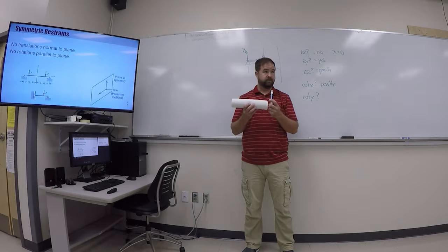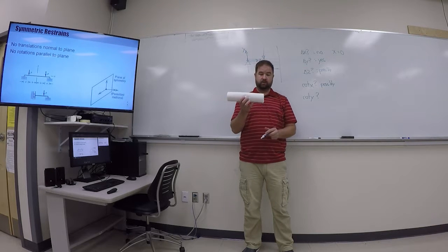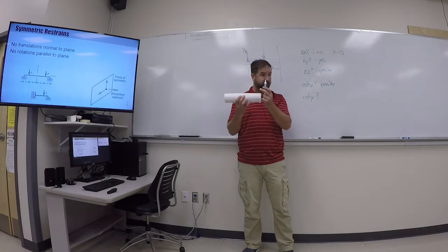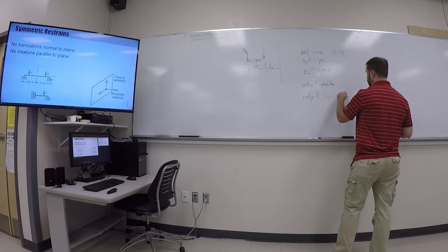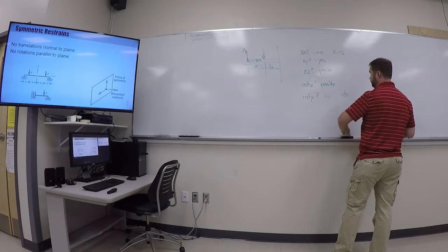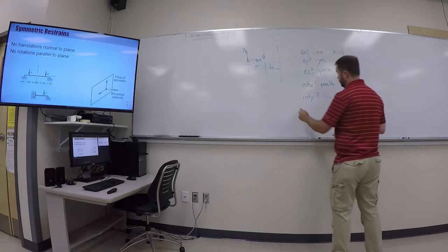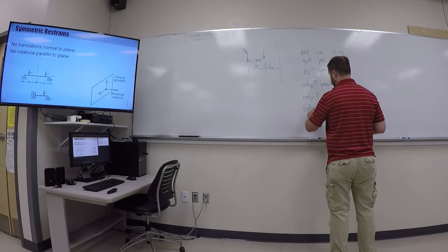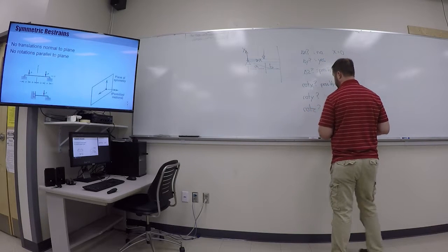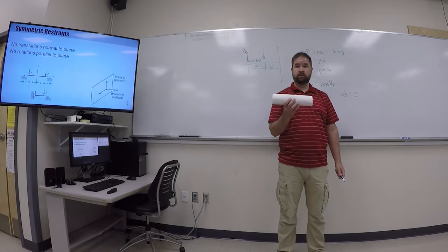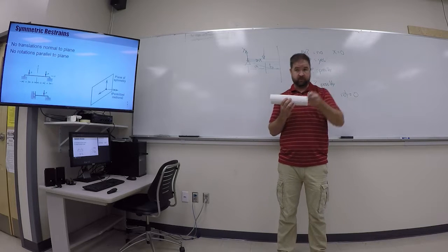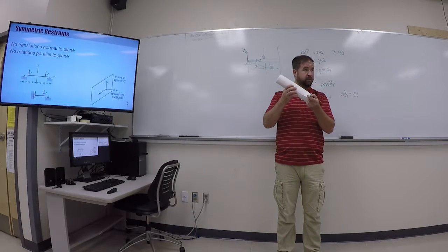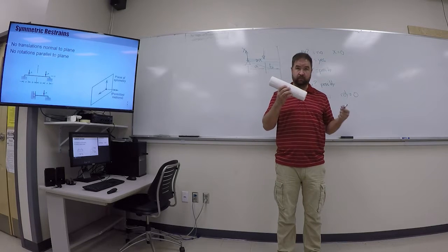Okay? Now, can I have rotations about x? Yeah, because notice my material does not break that perfect plane. Okay? So rotation about y, no. And so rotations about y have to be equal to 0. And then rotations about z, question mark. Going to be the same problem, right? Rotation about z was going out this way. Z's going straight out this way. So rotation about z is going to cause us to break that plane.